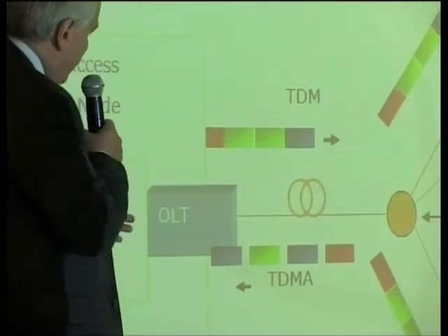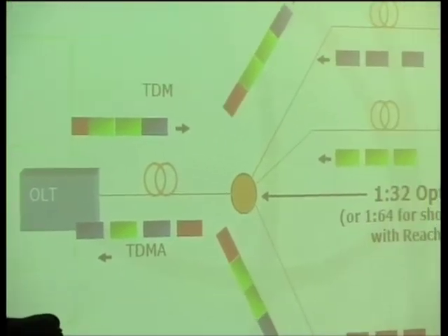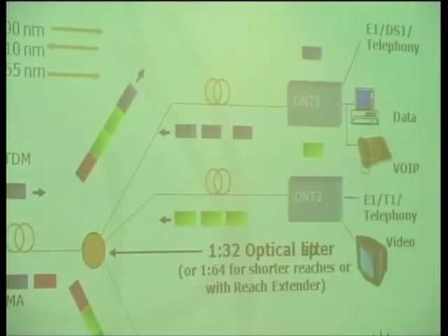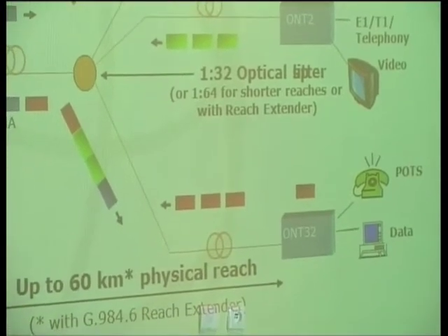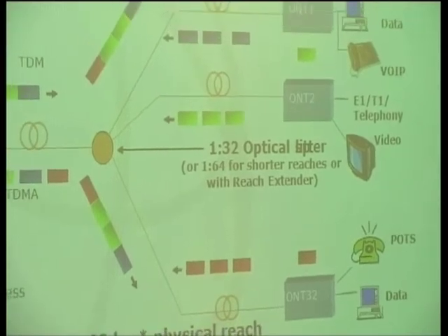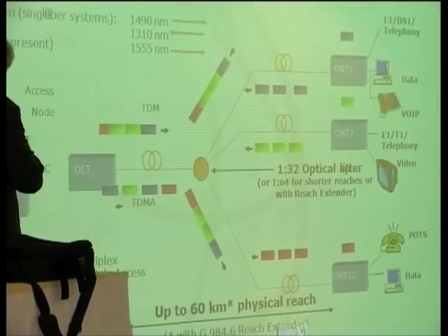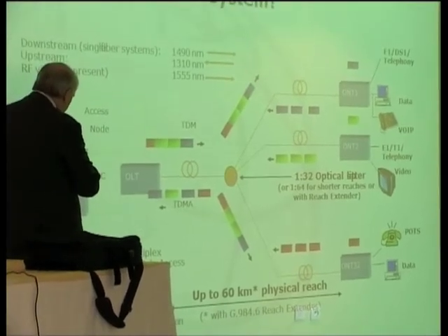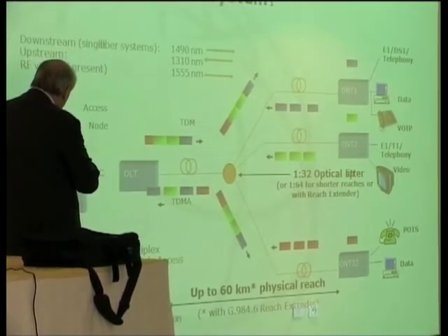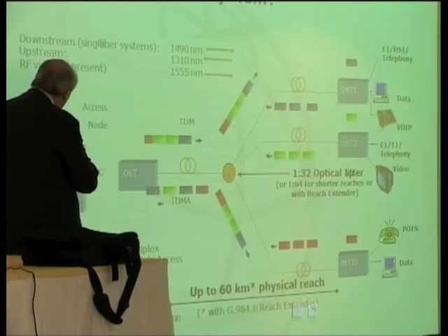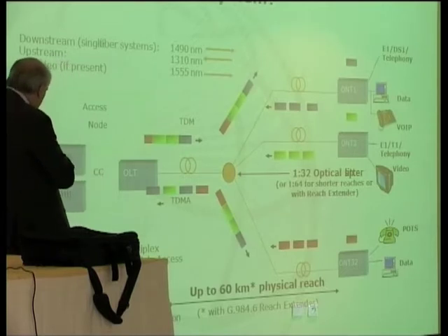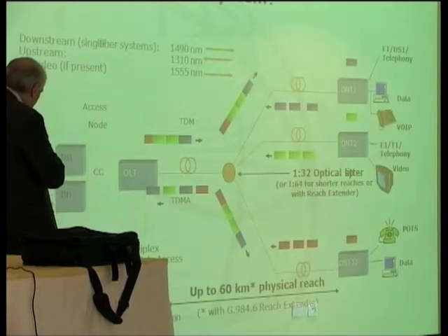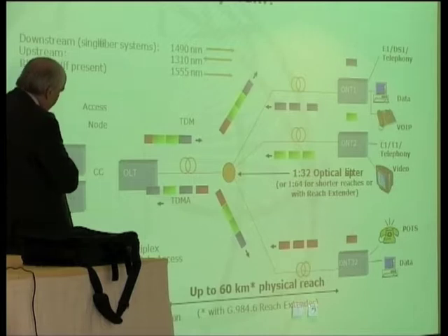The exchange is able to divide the services coming into the network and arriving from the network into narrowband services and broadband services, which means we can have here E1, which means 2.048 megabit per second, which means telephony, or this is the American standard. And on the broadband side, we can have gigabit Ethernet or some level of SDH.